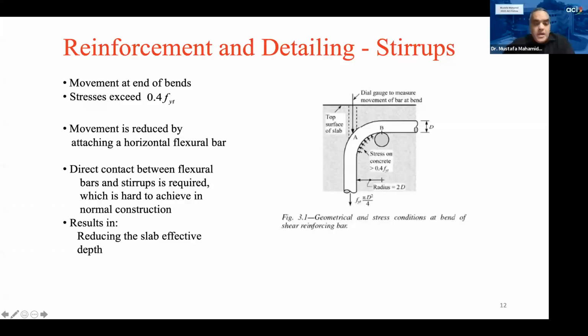If we have to use stirrups, the top longitudinal reinforcement of the rebar has to be reduced. So we have to take that into consideration. This problem can be avoided by providing mechanical anchorage. So if we provide mechanical anchorage, that can do it. The other option is mechanically anchored shear reinforcement, which is the headed studs here.